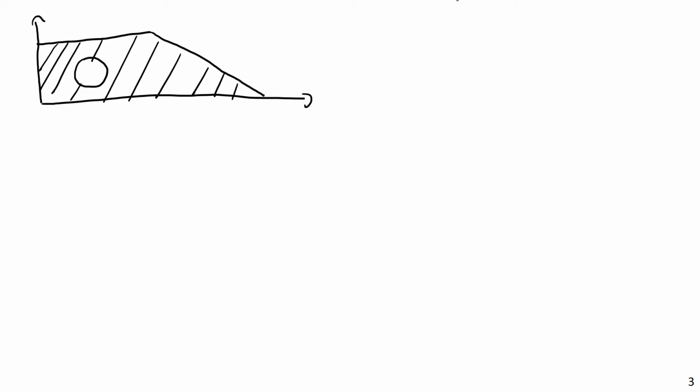Or, in something more familiar to mechanical or civil engineers, something like a wide flange shape. Something we've discussed before. This is basically a rectangle with 2 rectangular holes in it. How do you find the centroid of this? Well, actually this one's fairly trivial. If it's doubly symmetric, the centroid would still be right in the middle. But what if it wasn't symmetric? What if you had something kind of like this?